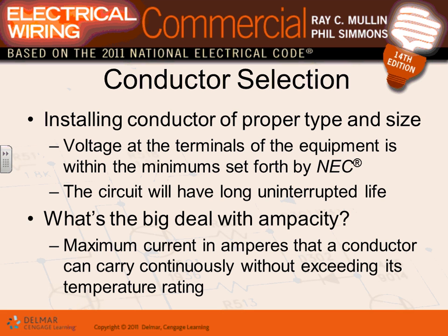Did you take the 90 degrees just because you're not going to overrate? We took the 90 degrees because for derating, you use 90 degree. That's why they give you THHN, guys, for 90 degrees. Because when you derate, you start with the very high amps. After you cut, you're going to end up with some type of a reasonable amount of amps.